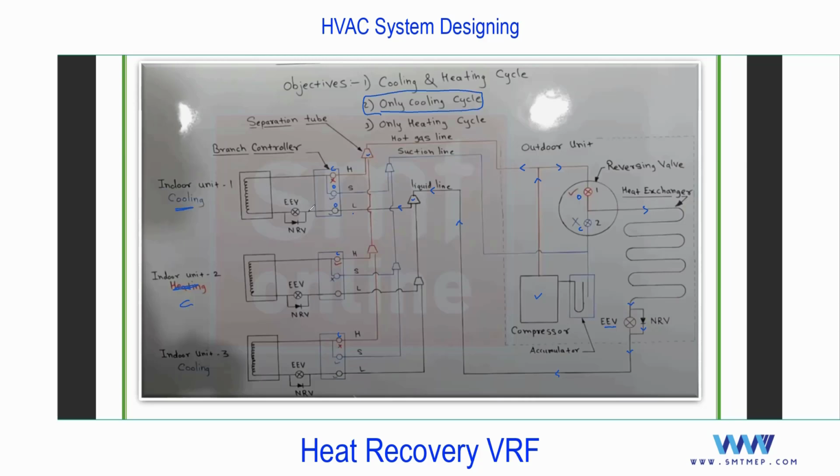So you see it will enter, and it will enter the electronic expansion valve, the same thing. Okay, and it loses the heat, pressure and temperature, and it will enter the evaporator coil. You know what will happen in this room. And since this valve is closed, it will enter through this valve which is open, and you can see, this is from other indoors, and then supply back to the accumulator here.